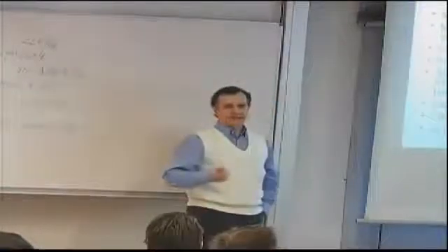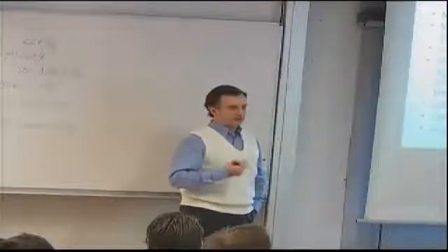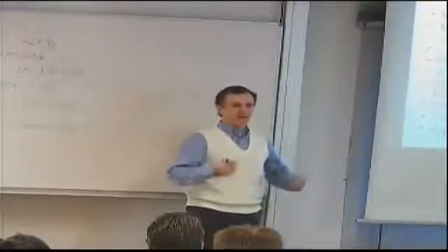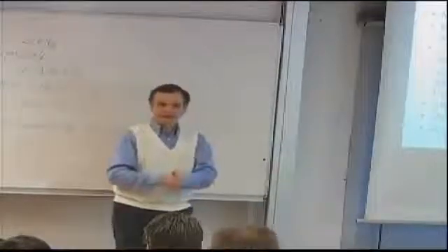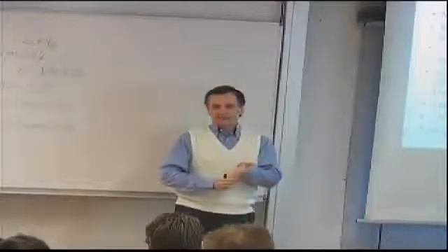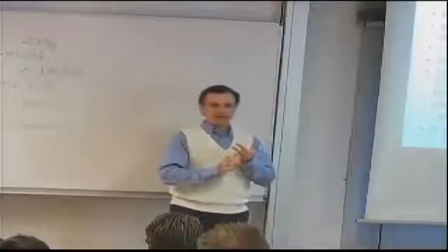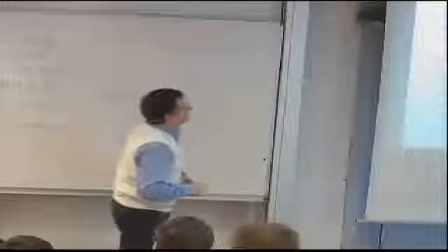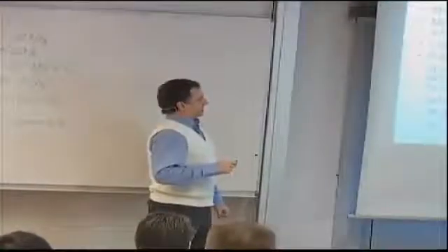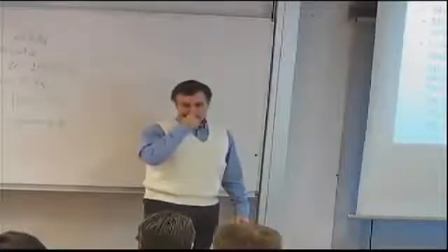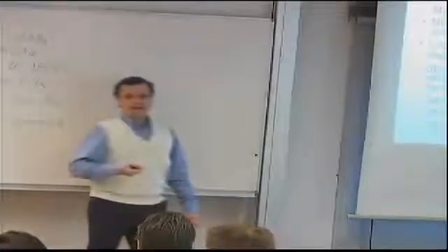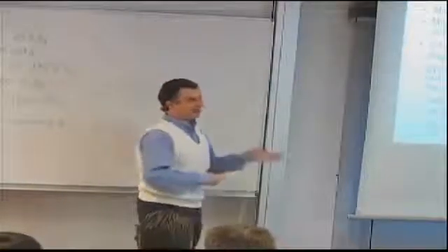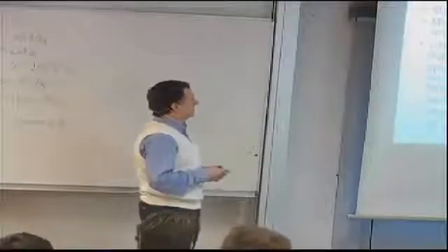Assembly cost is a very big deal, about 30 to 45% of the recurring cost in a composite structure. So if you can minimize assembly, and by assembly we mean putting parts together, that means minimizing the number of rivets, minimizing the number of parts, or maximizing their size, so co-curing a lot of parts, that can really make a big difference. Low maintenance, the airlines are extremely interested in that, especially if you have composite airplanes where you have to retrain all your personnel to know how to do repairs, how to do inspection, and how to evaluate what they are doing. They have been working with metals for decades, and now it's composites.